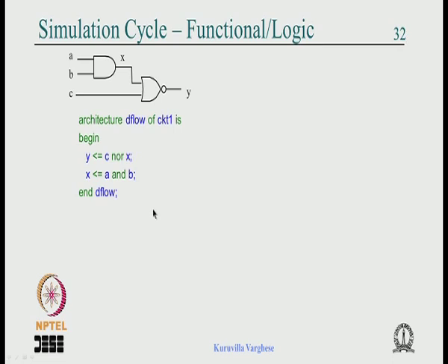At least conceptually there are many ways to handle it, but you just add a delay, some delta delay, and we say there is an event at 100 nanosecond, X is assigned at 100 plus delta delay. So an event happens on A at 100 nanosecond, X is assigned at 100 plus delta, now 100 plus delta is greater than 100 and maybe less than even the smallest next one, 101 nanosecond. So that is squeezed in between 100 and the next event.